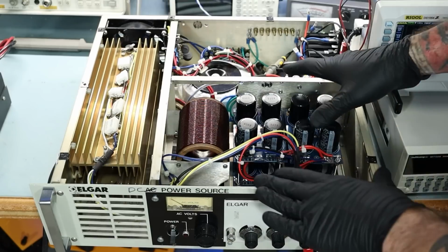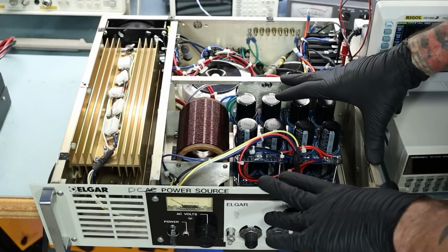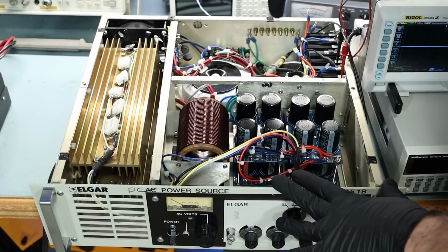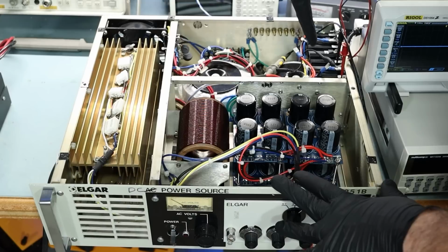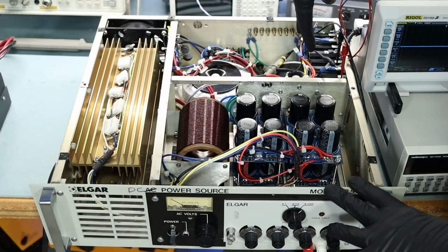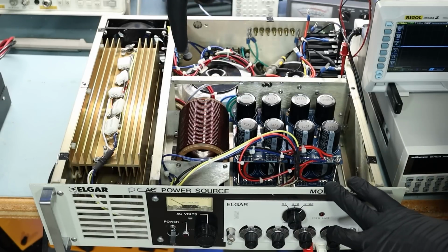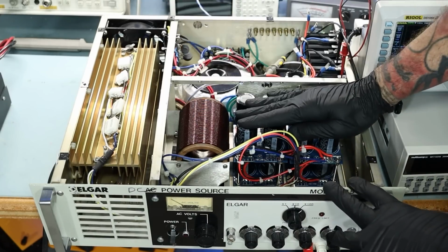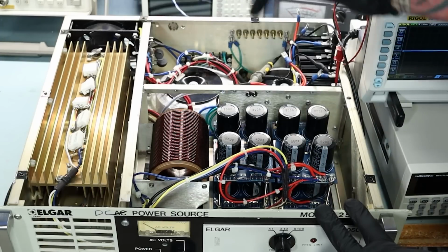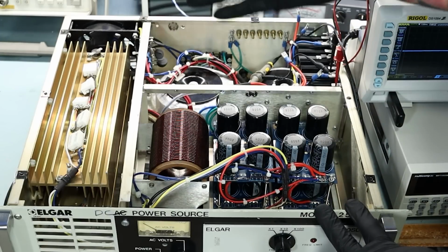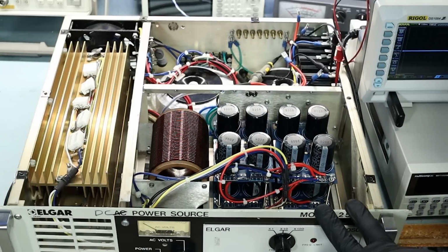Okay, this is our linear power supply. You might remember this from the Zener diode episode. But basically we have two transformers here that feed into two sets of full bridge rectifiers. That all gets combined into this inductor and then through this capacitor bank. So when we have those positive going pulses, these capacitors kind of fill in the gaps where those pulses start to drop off, right? Where the diodes are turning off.